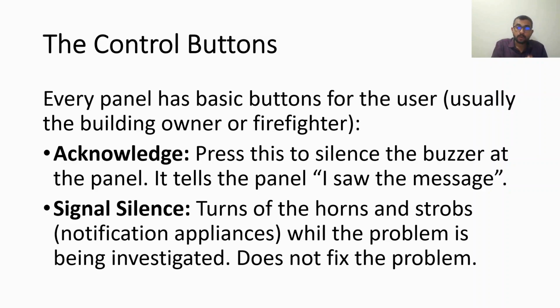It does not mean that the problem is fixed. Okay, maybe there will be some spelling mistakes, kindly ignore them. What I mean by the silence button is that whenever you press that button, the notification appliances will be silent. In case it is an alarm condition, it will be kept in silent mode, and during that silence condition, the problem will be investigated. Okay, that is the silence button.